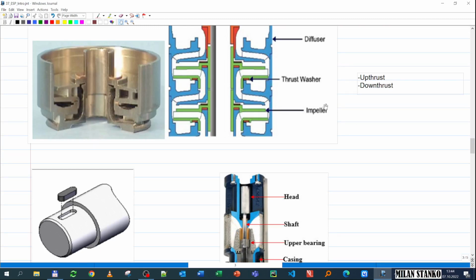so that when the axis rotates, when the shaft rotates, the impeller also rotates. So this key mechanism is what is used to fix the gray part, which is the axis, with the impeller. But one thing that this does is it only locks them both in place in the angular direction. So if this is rotating, the other one will rotate, but it doesn't lock them in the axial direction. So still the impeller is able to move up and down with respect to the shaft.